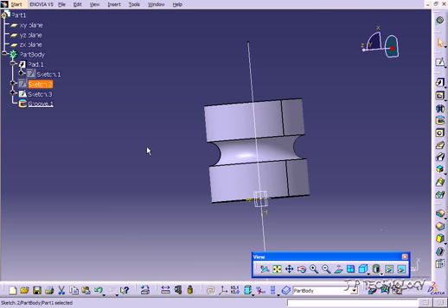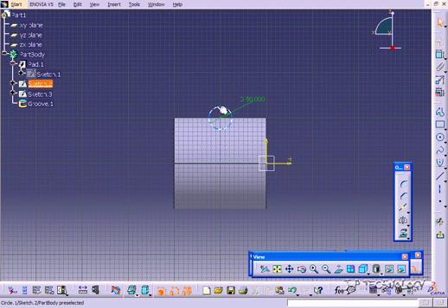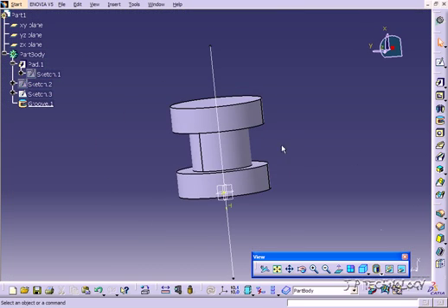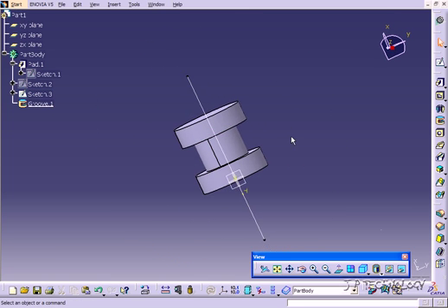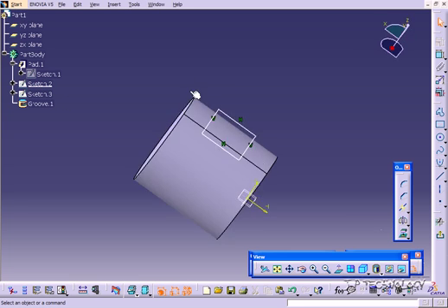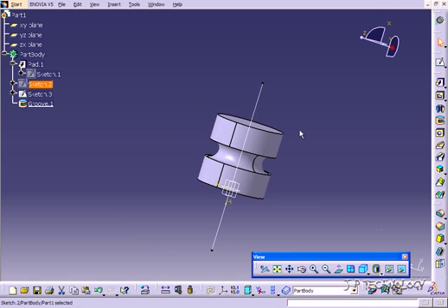Now let's click on Sketch 2, and let's double click on it, and this is our profile. So let's change our profile. Let's draw a square around it, and let's delete the circle. And when we go to click OK, it's going to rebuild, and we're going to have the square instead of the circle. And you can see that we have the square cutout groove all the way around rather than the circle. Now let's go back into it, and we'll change this back to a circle. Don't worry where you're putting the circle, just make one. Click OK, and now we've got the circle back.